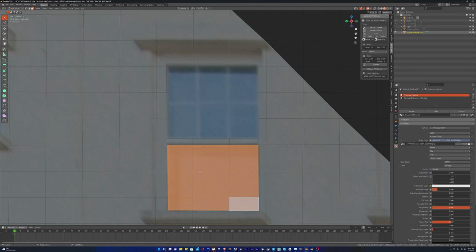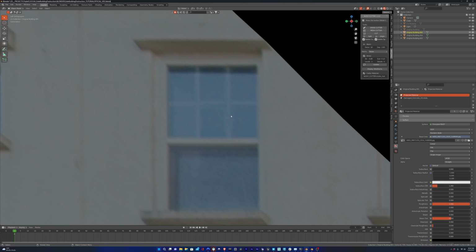And if you just want it as one plane, you can select all of them, right click and hit dissolve faces, and that'll just merge them all into one. And then what you can do is hit P and then separate by selection. And then select this, P, separate by selection. And now these are their own objects. So you can actually texture these as a window now. So let's just go ahead and do that for this one.